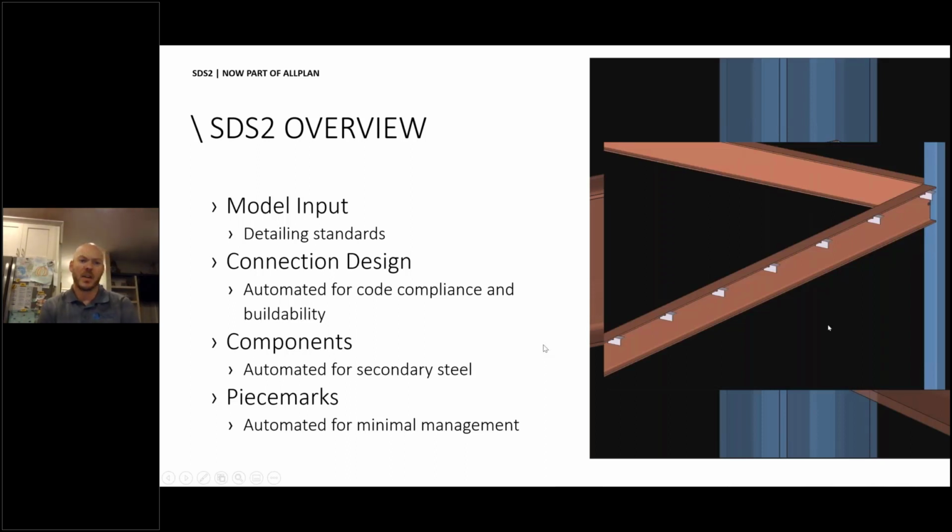And then automation for different things, like outriggers in this case. We provide components, which are parametrically driven tools. This is a really simple example of adding angle outriggers to the edge of my beam, where I specify a spacing, or it could be a number of spaces. Based on the length of this member, it automates that, figures that out, calculates that, and adjusts as necessary.